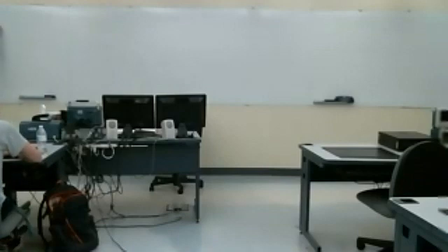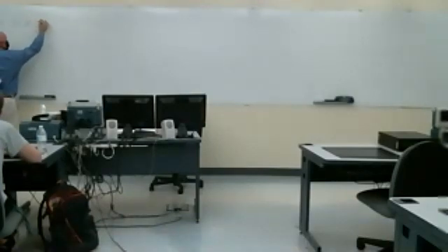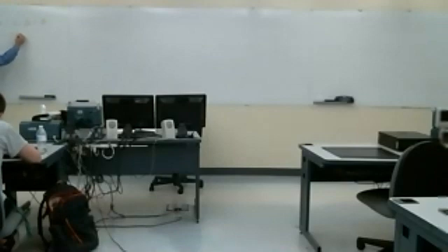Since ZL is j omega L, and ZC is 1 over j omega C, or minus j over omega C, we can factor out omega L minus 1 over omega C. There is a particular frequency at which that series combination looks like a short.